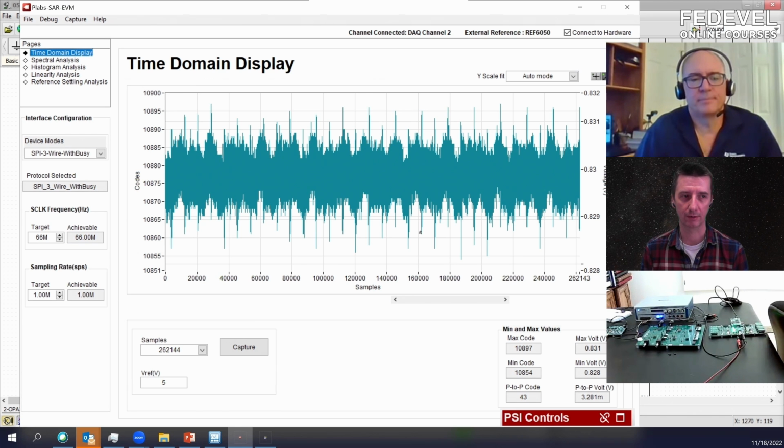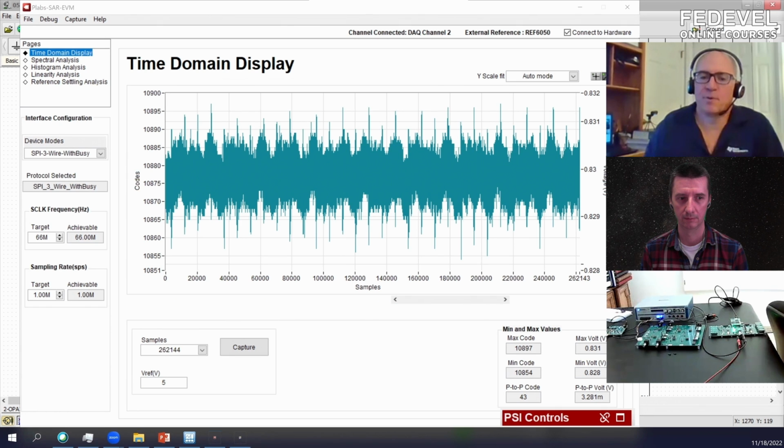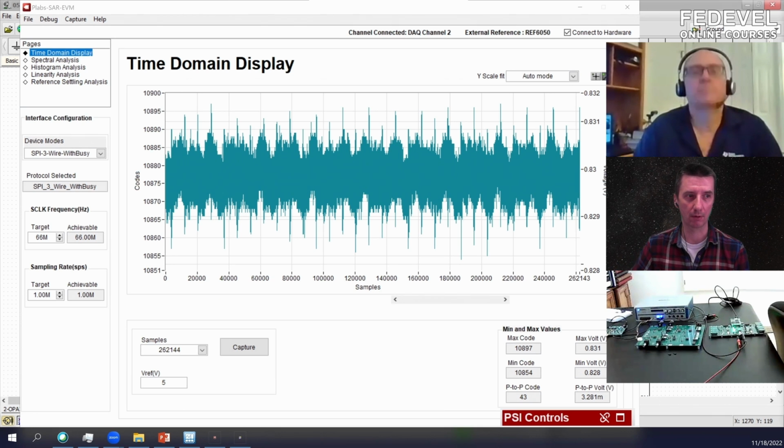So for an AD converter, normally you don't really use a filter on the input. You can do everything digitally. Well, you do. You still use filters on the input. And to the RF example with the walkie-talkie, there's no digital filter that's going to eliminate that. So you would want to get rid of that high frequency pickup with an external filter. If there's an amplifier, the filter could be on the amplifier or before the amplifier. Sometimes the A to D converter will have a simple RC filter on the input, and it just connects directly to a sensor.